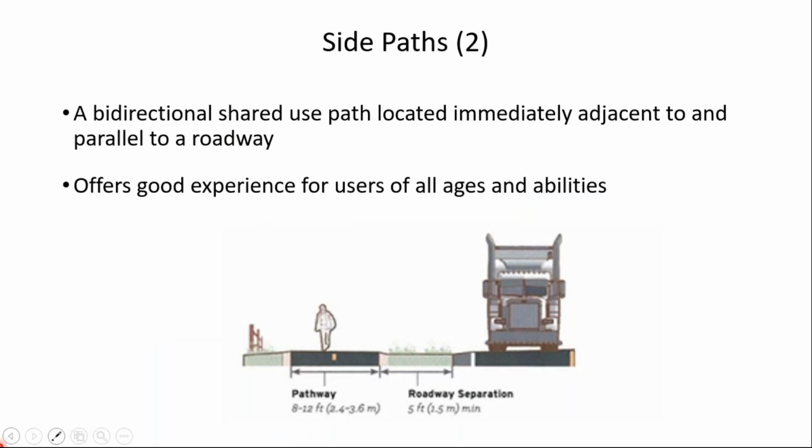It's typically bidirectional, and it's been found to offer good experience for users of all ages and ability. And as I mentioned, typically the minimum separation from the roadway is 5 feet. And then the pathway would follow the shared use path design guidelines.